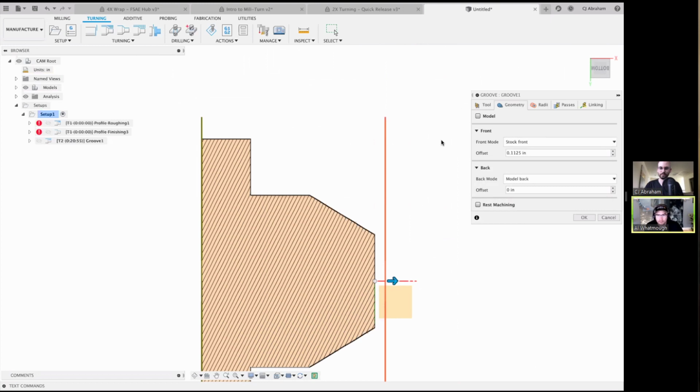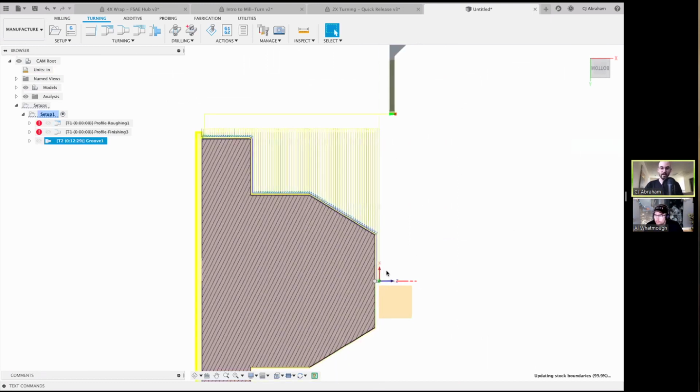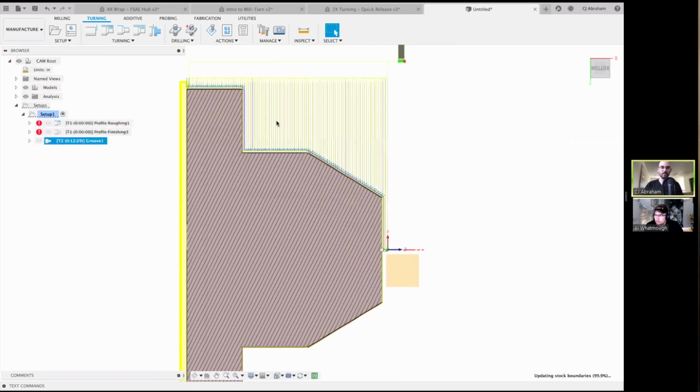Then you have to go back through, and every spot where you put 1/8 of an inch, you need to replace it. Whereas his muscle memory is, I'm going to link it to the correct value so that my intent is preserved when another change takes place. Exactly. And now that I've put that expression in there, it just goes the distance that it needs to in order to fit the tool.